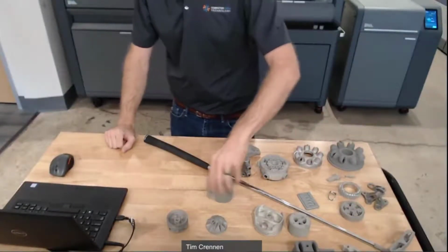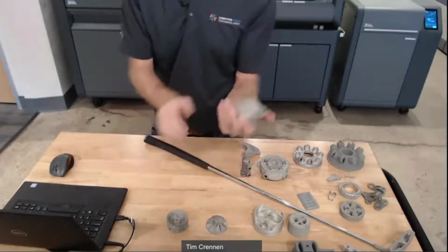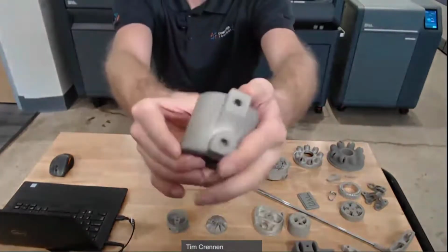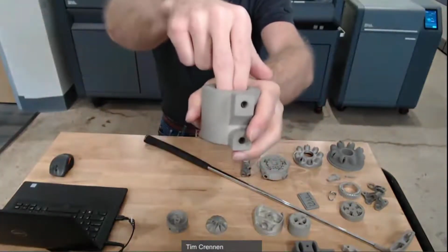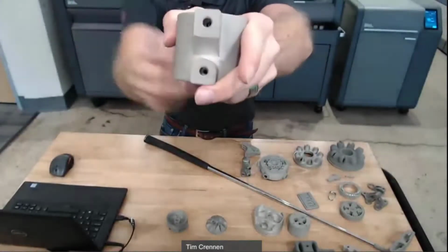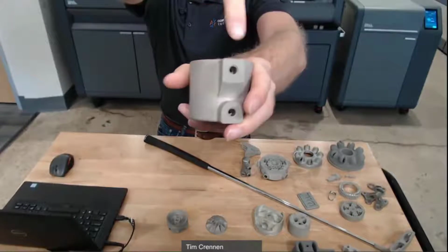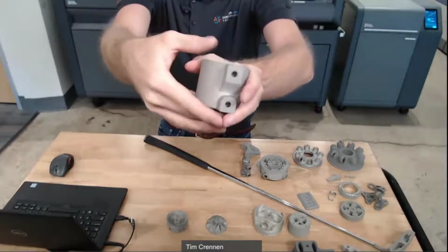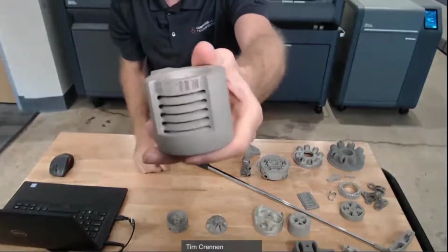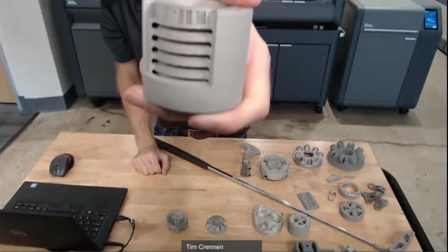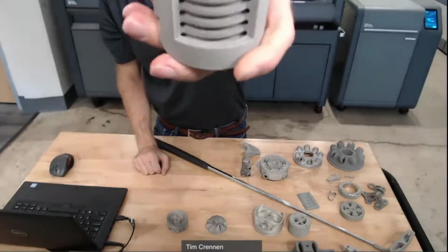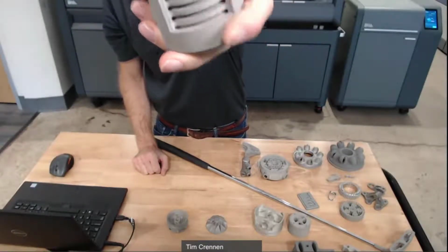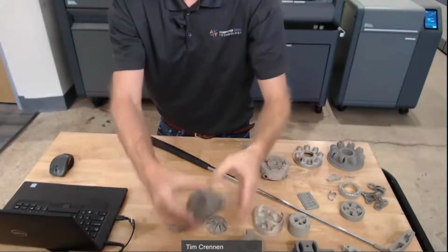We can also do other parts that are really cool and complex, but they don't look like it from the outside. So this is actually a really neat part that has internal cooling channels and everything built into it. So basically, it mounts on, something's going through here to be cooled, and you have your inlet and outlet right there on the front. It actually has spiral tubing wrapping all the way down through this part and then coming out. So there's internal tubing in there. So it's actually able to cut away the outside of it, so you can actually see all the internal spirals going through there. You also get a little bit of insight into the actual structure. So when the parts get too thick, we don't print them completely solid, and you actually have a little bit of infill.